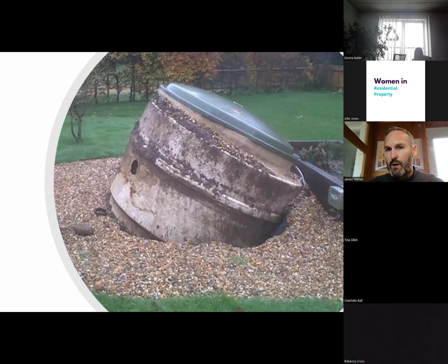We're then at a situation where the customer has their annual empty, it's normally annually, of their sewage treatment plant. But the problem is that these sewage treatment plants, certainly from the 60s and 70s onwards, are made of a material similar to that of the hull of a boat. And funny enough, they are really good at floating. So in this scenario, we've got that buildup of water because of the sustained rainfall. So we've got hydrostatic pressure, that body of water sitting in the ground around it and underneath that asset.